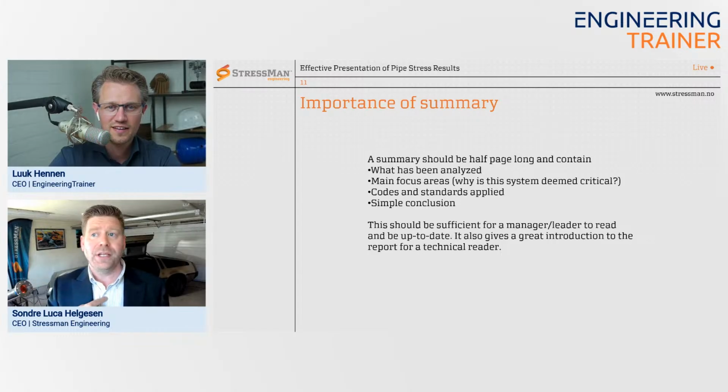And also, let's say somebody put in the stiffness of a support, and I'm curious about that support, then I can read all the details that the stress analyst put into it. So input echo is something that I hold sacred, that should be with every report.